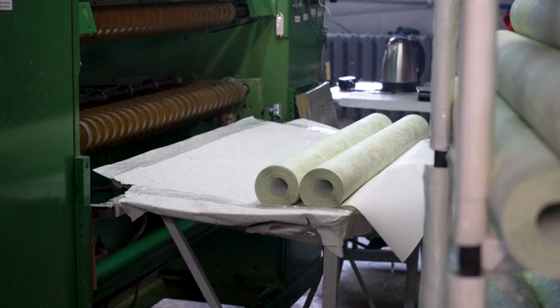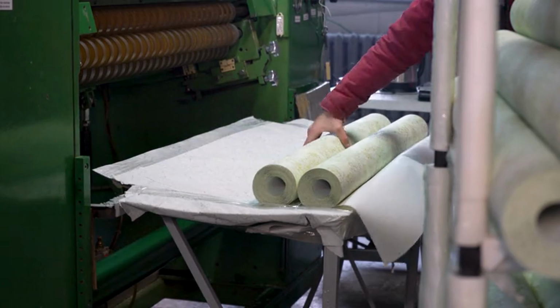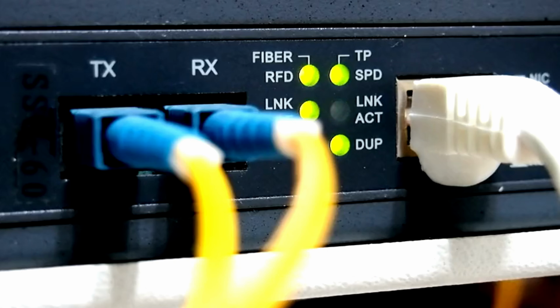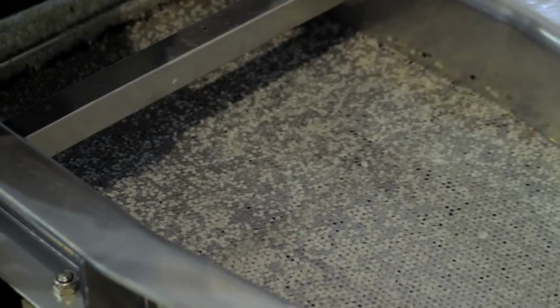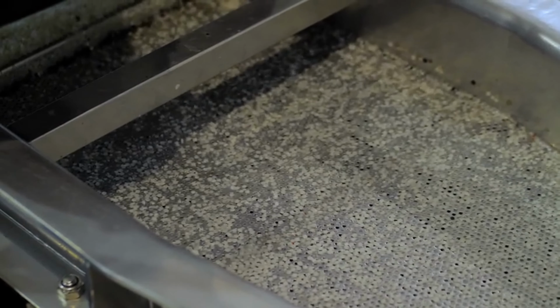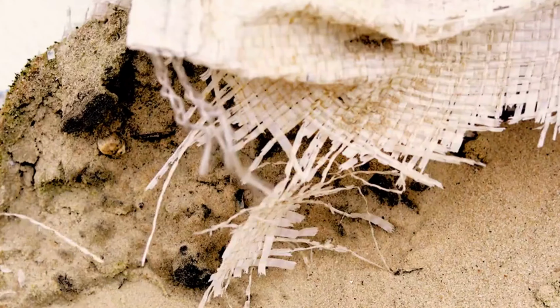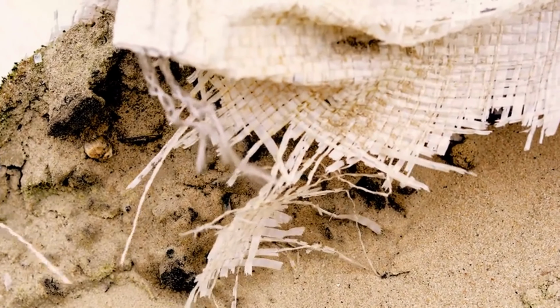5. Paper formation, sheet making. The cleaned pulp is now ready for sheet formation using a Fourdrinier or cylinder machine. Key steps. Headbox, fiber distribution. The pulp, 99% water, 1% fiber, is sprayed evenly onto a moving wire mesh. Fibers begin forming a mat as water drains.